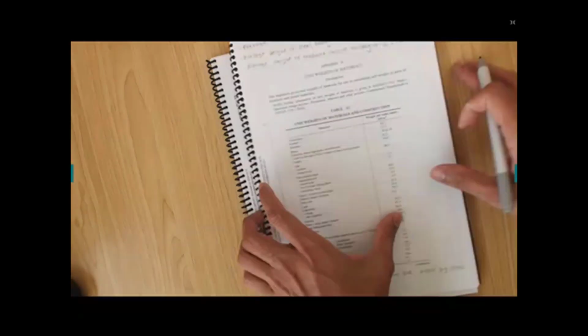If you use the same standards and they did not give you the live load, but they say it is a house, I believe self-contained domestic and residential, stairs and landings in self-contained dwellings, you have a uniformly distributed live load of 2 kilopascals.